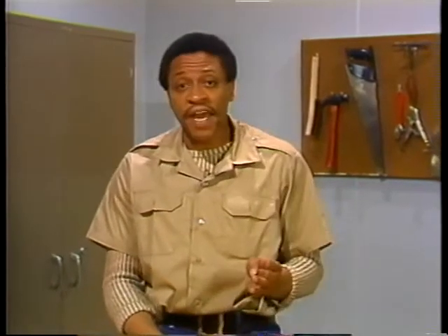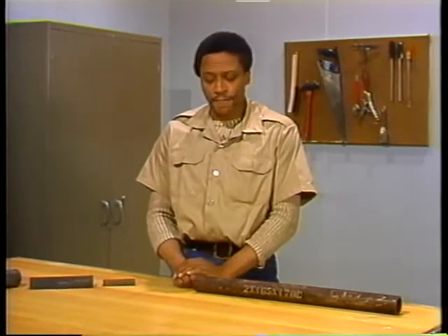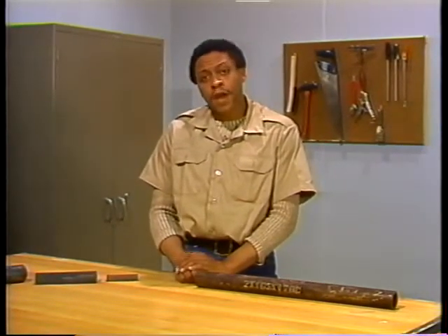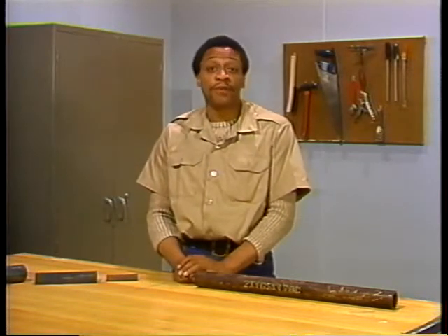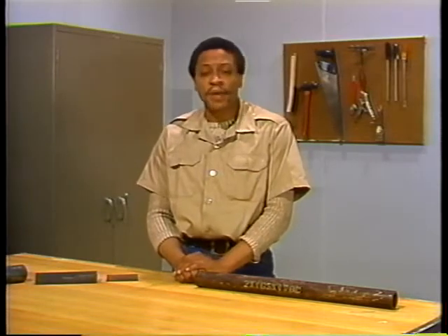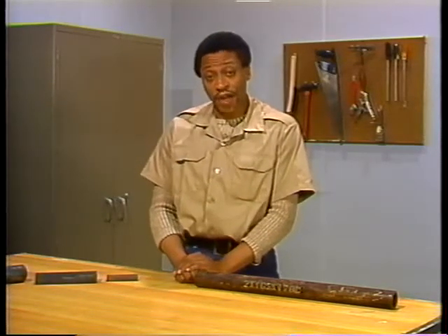Mechanical stress is another basic cause of tube failure. Mechanical stress is the result of pressure, thermal expansion, the weight of the tubes, and vibration. Tubes are built to withstand a certain amount of mechanical stress, but excessive stress leads to failures. For example, boiler tubes are designed to contain pressure. Sometimes extreme pressure can burst the tubes, but that isn't common. What's more common is that something will weaken a tube and normal pressure will rupture it.